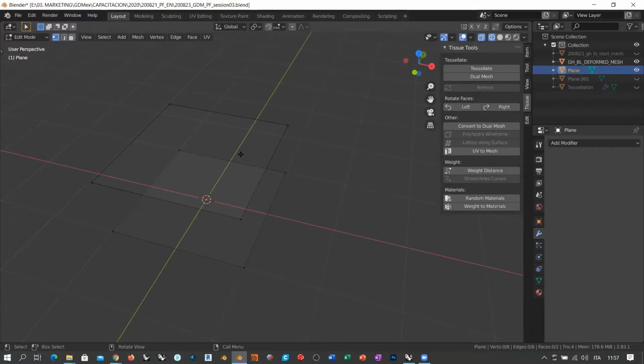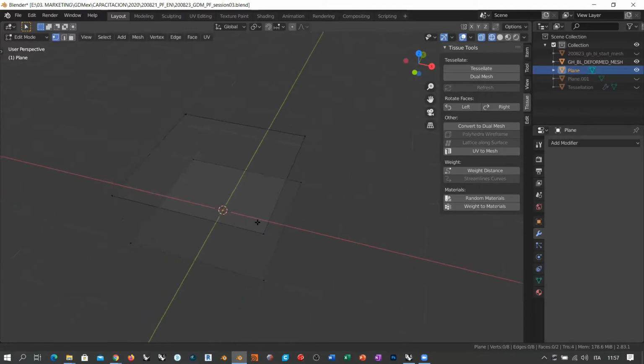Why? Because remember that in Grasshopper, the shortest walk algorithm needs a line structure, or rather a truss structure made up of lines, so that the shortest walk can be calculated along these segments. So what if we provide something to Grasshopper made up only of lines? Okay, so what I'm going to do right now is something like this.